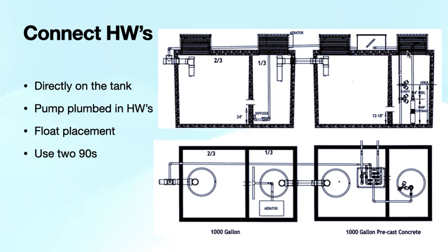We'll also provide a 1-inch union so that in need of servicing the pump at a later date, you're able to just disconnect the union and pull that out. But that's where that is. We'll provide the floats. The float placement is pretty simple. We'll have the floats already pre-tethered on brackets that you'll just attach to a 1-inch line of PVC that can be attached to the riser here to hold in place. But it's a 2-float system.